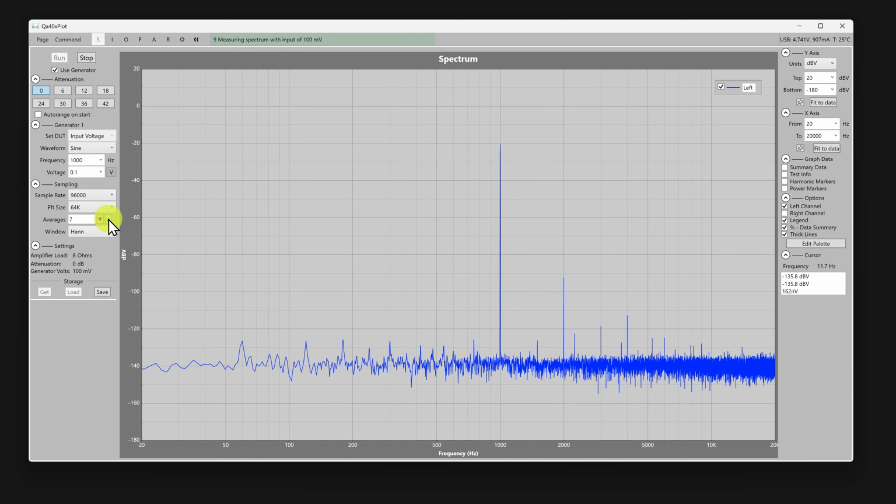And if we increase the number of averages, it'll get pretty darn skinny down here, but you're not really getting much extra information other than we can see the peaks pretty nicely. And those are what's important. So when you're looking at this graph, the peak in the center is the fundamental, the sine wave frequency. And we expect it to be at the amplitude of whatever device we're looking at's output. The other peaks are all distortion or noise or you name it. They're not good things.